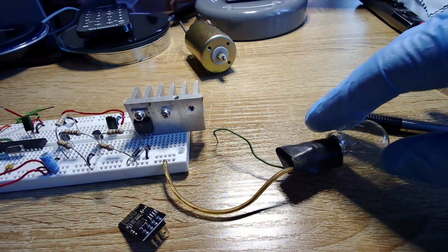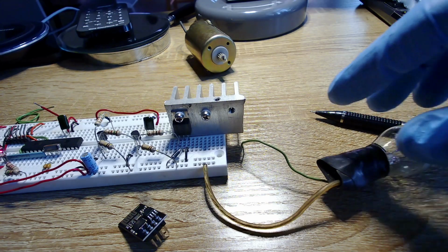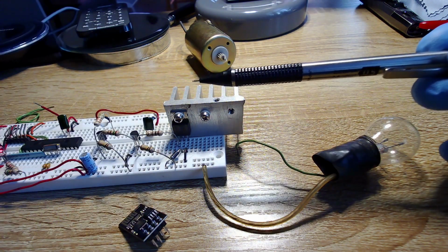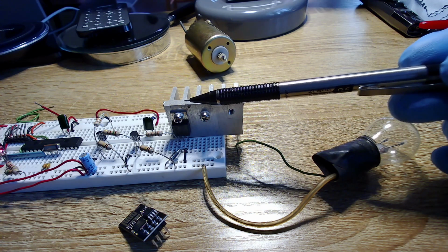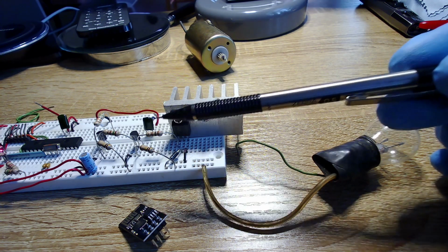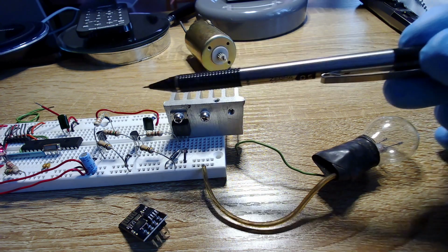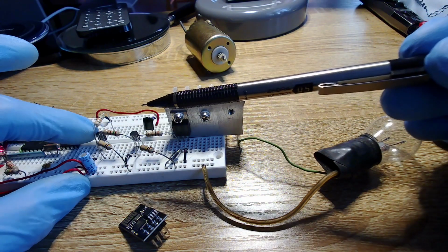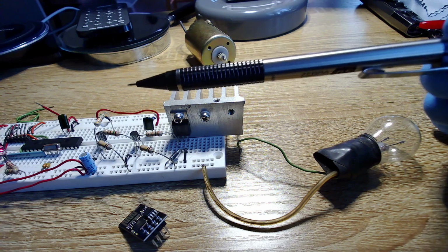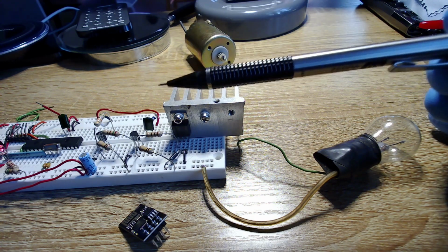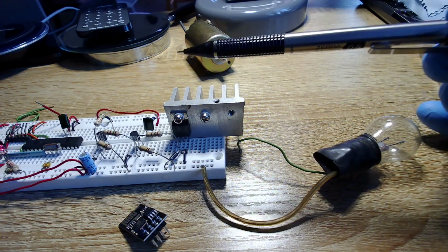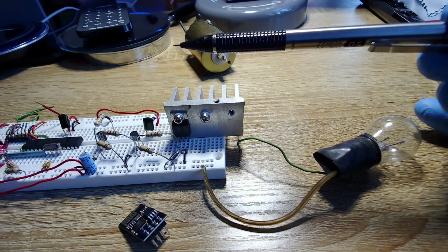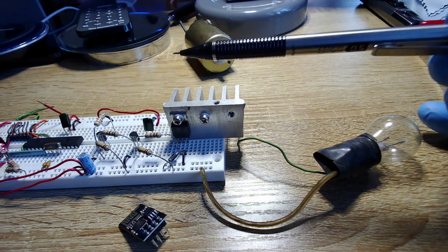So this video is about this circuit here, which is basically 3 items. What you'll see most of the time is that all this circuitry will be packaged up inside one nice small package. I should have had one handy. Sometimes you'll have Darlington transistors. That's very common. Darlington transistors are when you pair up 2 transistors and you're basically multiplying their current amplification, which is a whole discussion, because it's not like what you think of as amplification, which is typically voltage. Anyway, I digress.